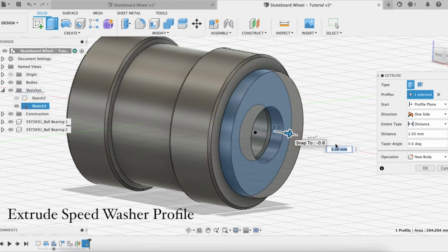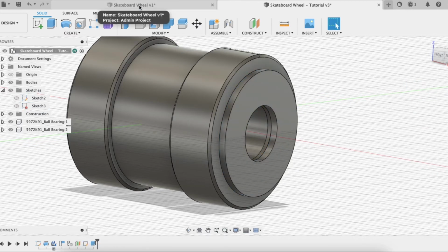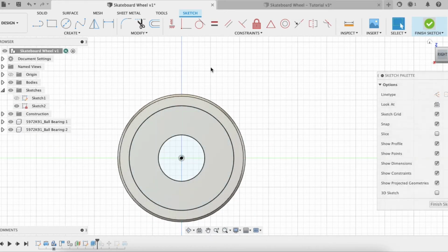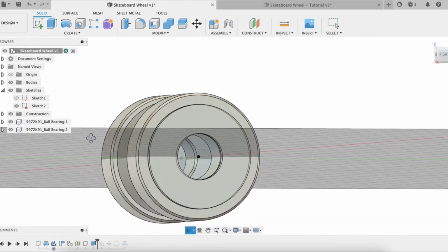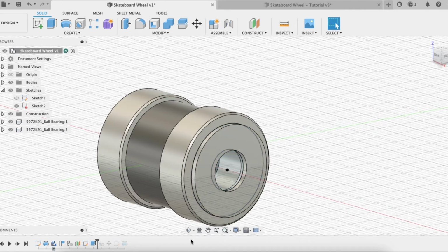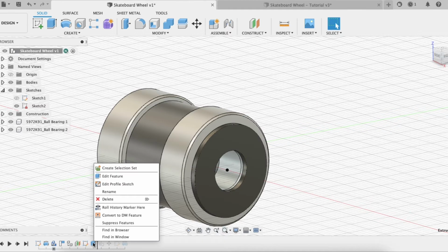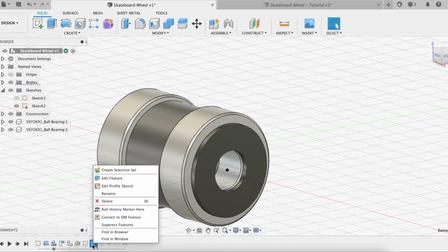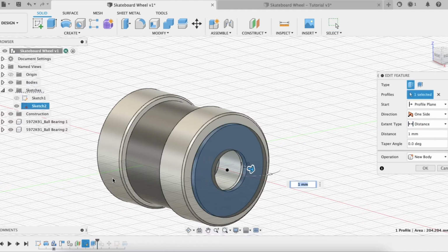For right now, I know we're going to just extrude it, and I'm going to set it at 1 millimeter for now, and then I'm going to reference my drawing here to see the thickness of the shape that I created. So to do that, you can right-click on the command or the operation that you created in this history down here, and then you can hit Edit Feature. Okay, and it looks like I did do 1 millimeter.